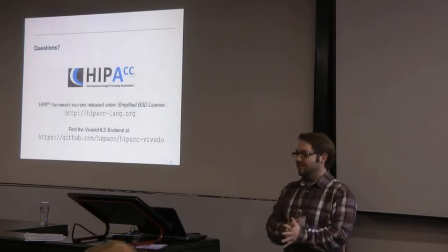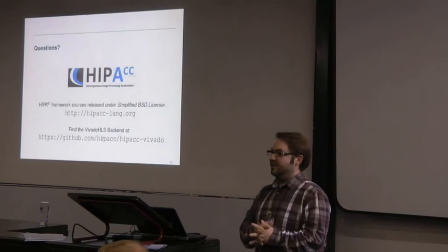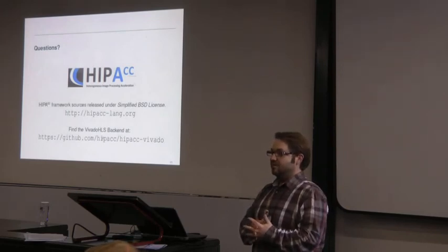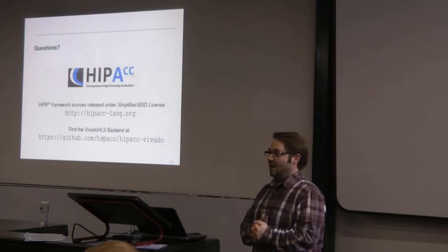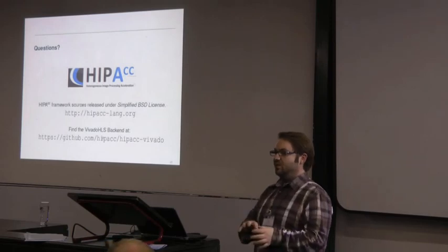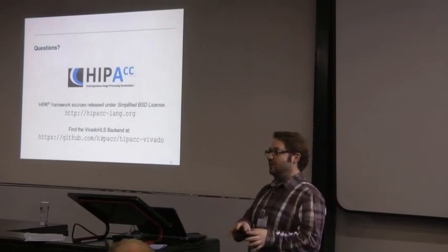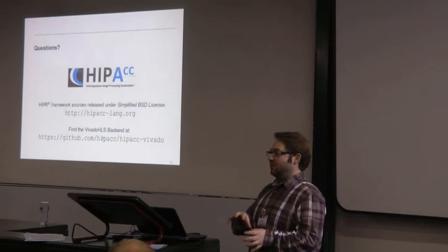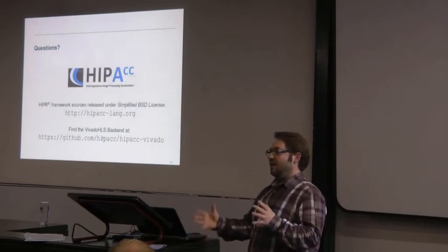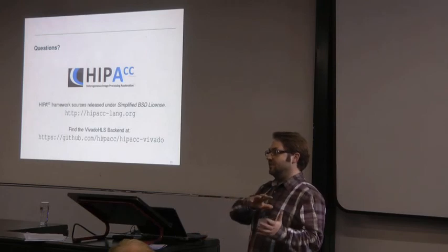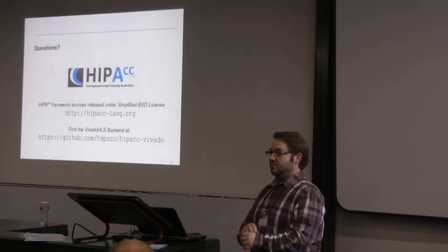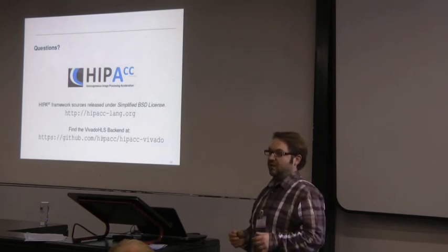For these comparisons between FPGA and GPU, the GPU presumably uses floating point math, but in the FPGA are you using fixed point math, or is it also floating point to the same precision as the GPU? It is the same code. So if we instruct the GPU to use floating point, we also use floating point on the FPGA. If we instruct the ARM to make use of its vector units, we've created a high-level synthesis design that can synthesize vector units in Vivado HLS. And it would instantiate Xilinx floating point cores then? Yeah, of course, as Vivado HLS does.